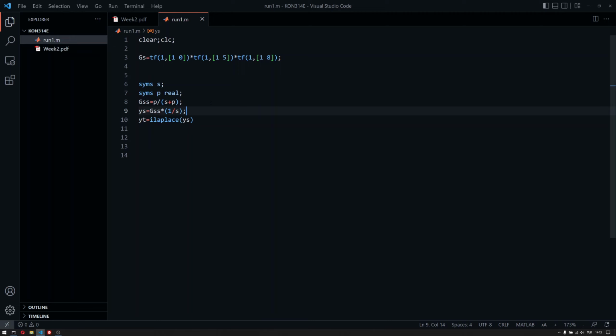Overshoot is 0. They have a settling time 3.91 divided by the absolute value of the pole. If it's a stable one, it should be on the left half plane. And that's it. We also know the peak time, rise time, but they are not really that important or relevant at this point because it is a first order system. It is an exponential term. And yeah, the settling time is relevant, but the other ones, of course, we have formulations for them, but for now, not really important. What about second order systems?